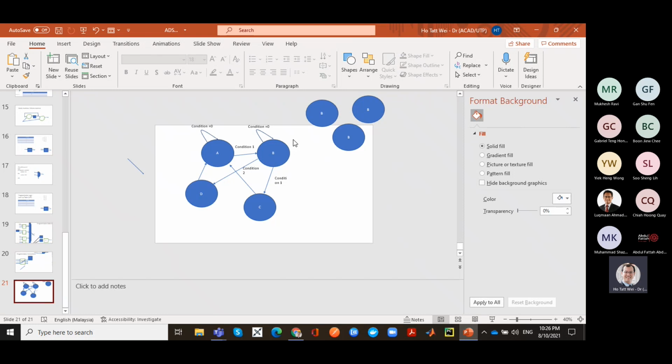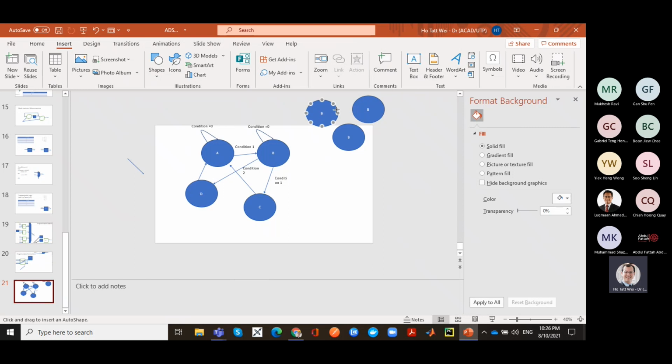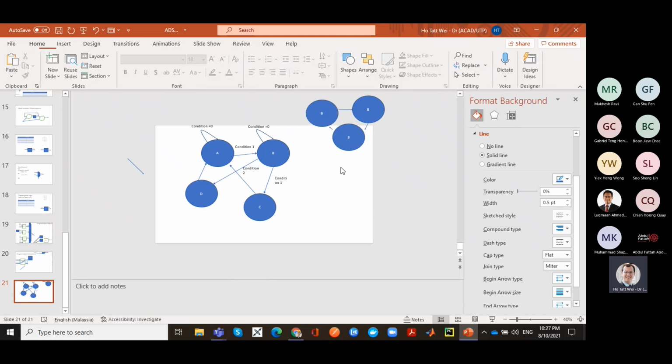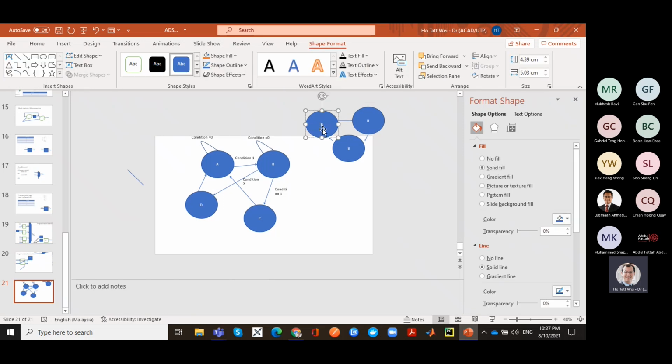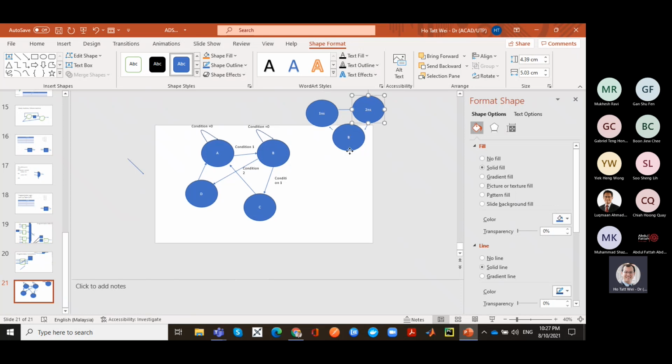And what would be the simplest example? The simplest example could be something like a timer function. This is my favorite example to showcase this, where basically I can have a timer, and for the timer I can implement a state transition diagram, and that state transition diagram is nothing else but a counter. So with a counter, there are no conditions, right? So let's say I count 3 clock cycles. In this case, I count 3 clock cycles. Maybe your clock cycles are 1 nanosecond apart. So this is 1 nanosecond has elapsed, 2 nanoseconds has elapsed,